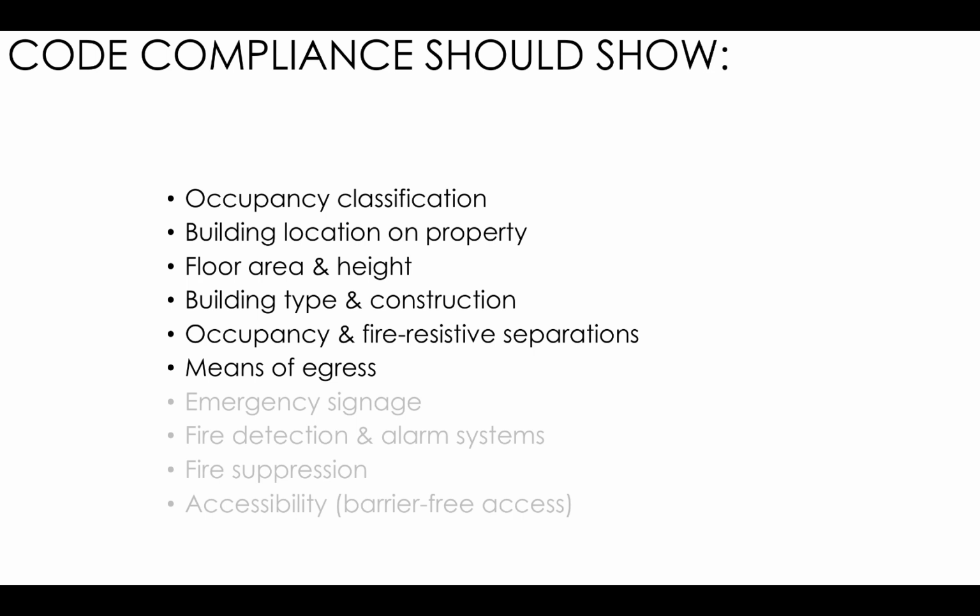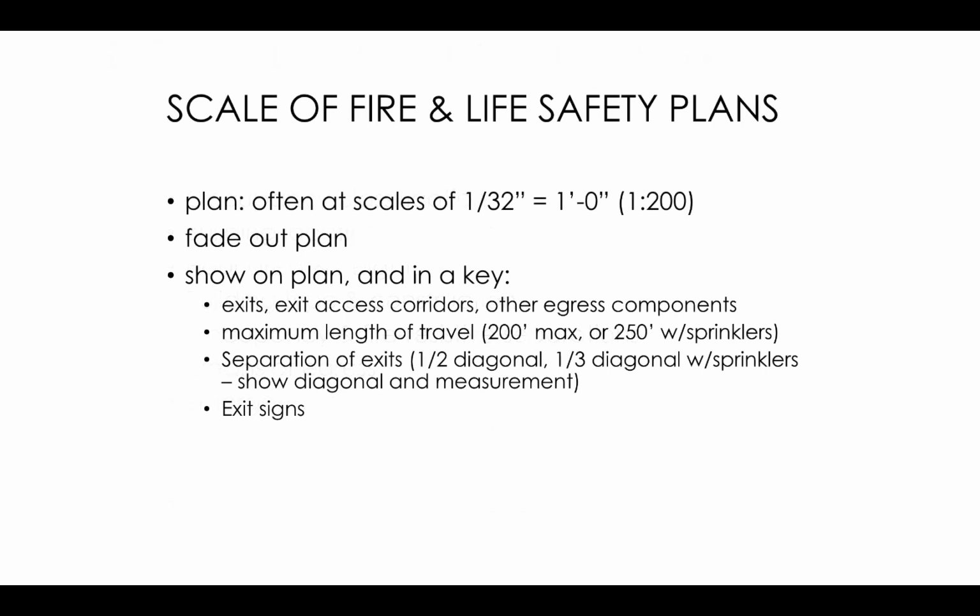But then the last piece, the means of egress, is really important, and it has a very large effect on your project, because the number of exits and having a compartmentalized path of egress, if it's called for in that project, really affects the way a project is laid out. So you need to make sure you get that right early on. You would not want to have to add things like an extra stair later on or extra doors. Other stuff on that list we'll cover later.